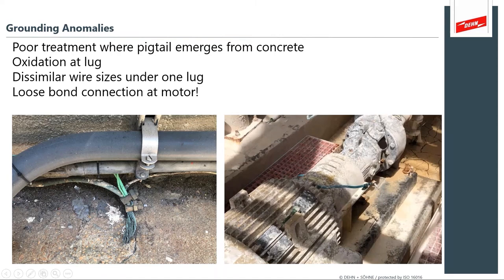Off here to the right, you've got a motor stanchion grounding that's not even connected. So it's going to be very difficult to troubleshoot problems with the instrumentation when it's floating bonded. So here we have a direct problem where the instrumentation and the earthing on this motor is going to lead to instrumentation failure because the motor is not bonded.